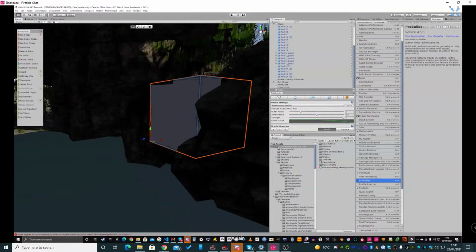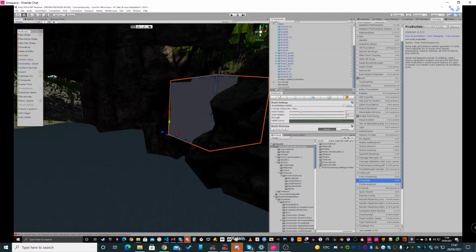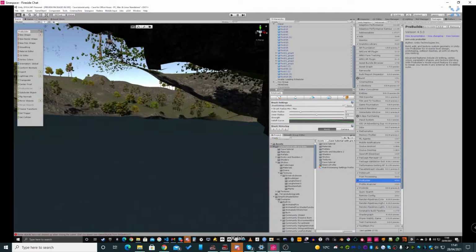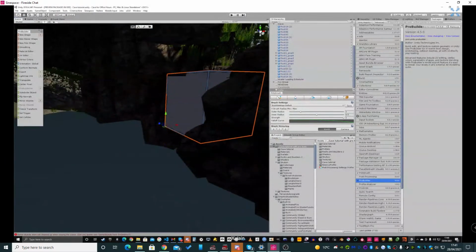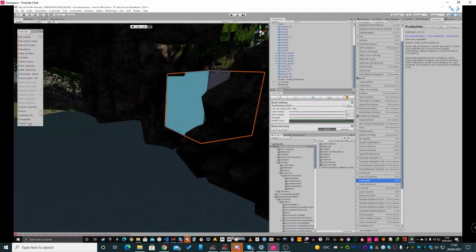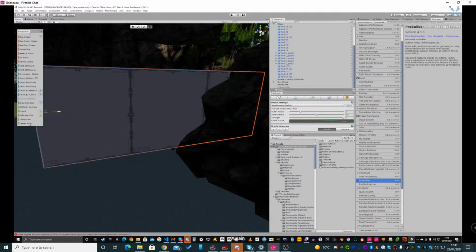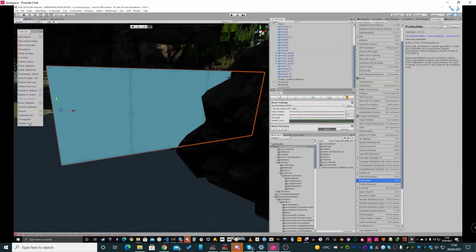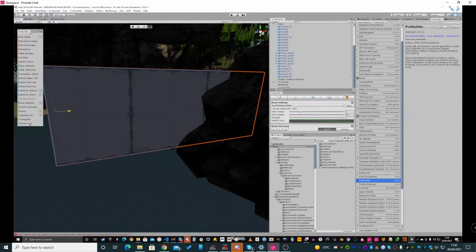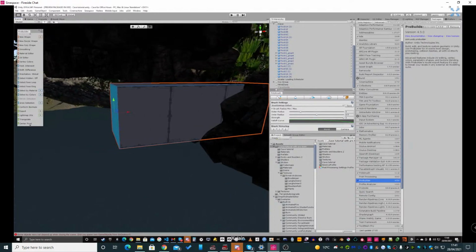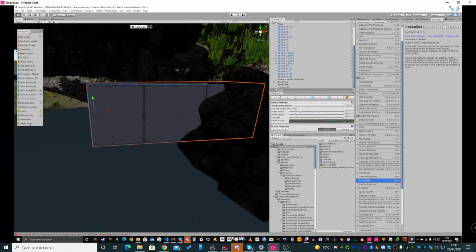So what I want to do now is extend this side, obviously, to make my tunnel go down there. And you could do this just by hitting this side and going like that. But the problem is that's a quad on this side. It's one whole quad, and all I'm doing is stretching that quad out and mucking up the topology. Basically, it's not going to be right, especially when I start subdividing and there's other objects later on, like the bigger part of the cave. The topology is going to all go wrong.